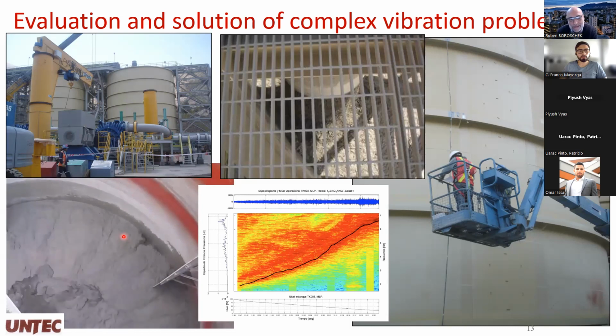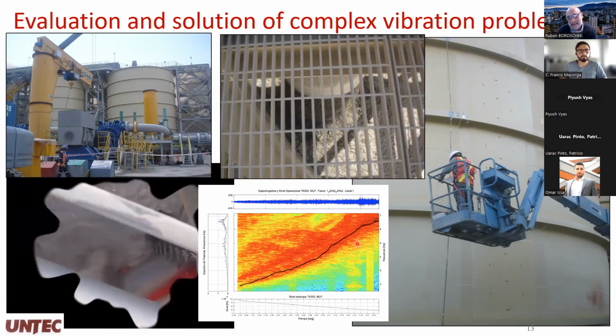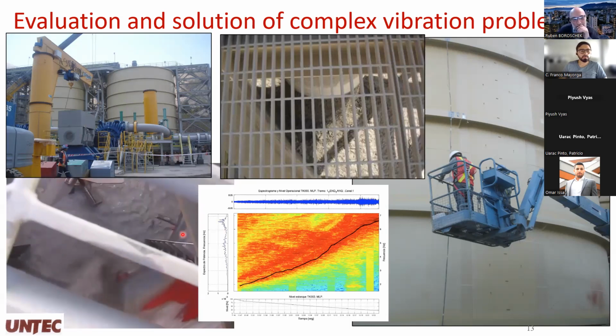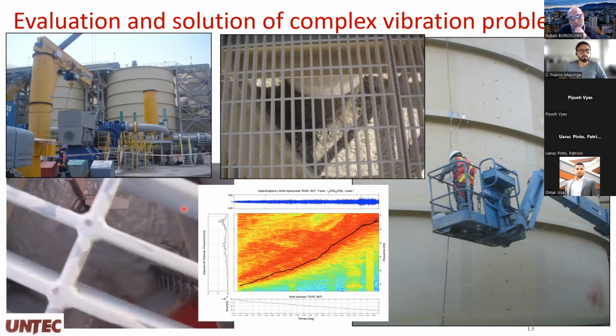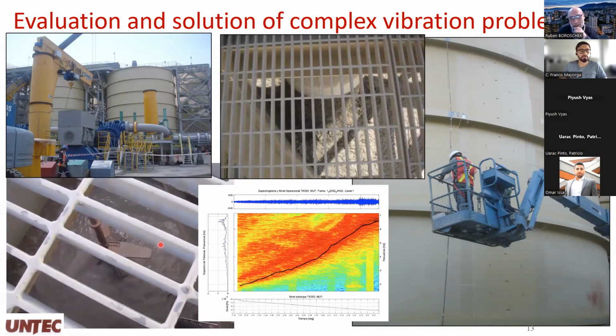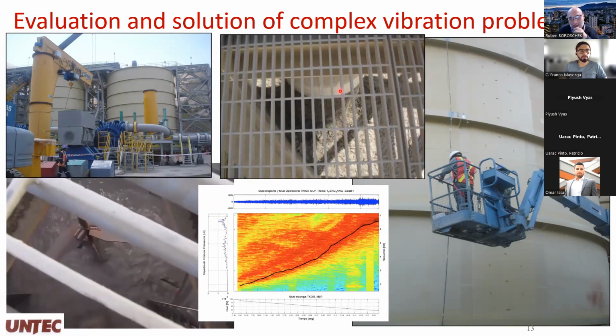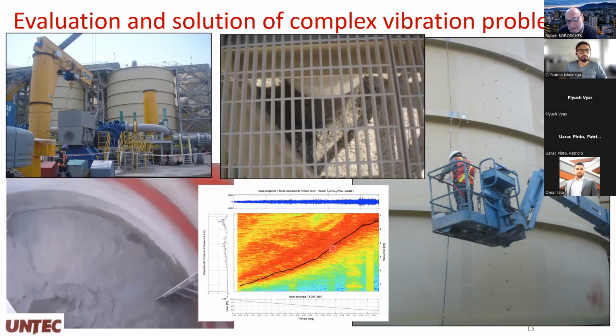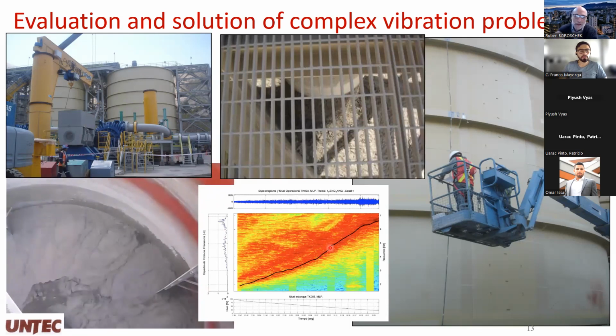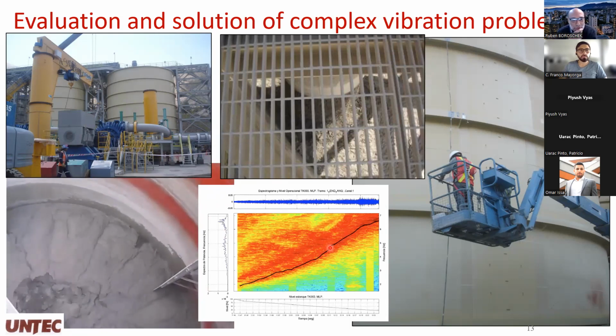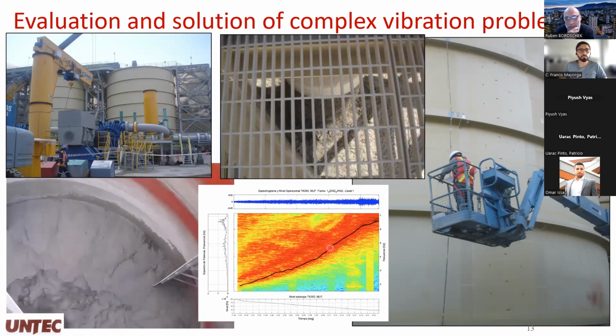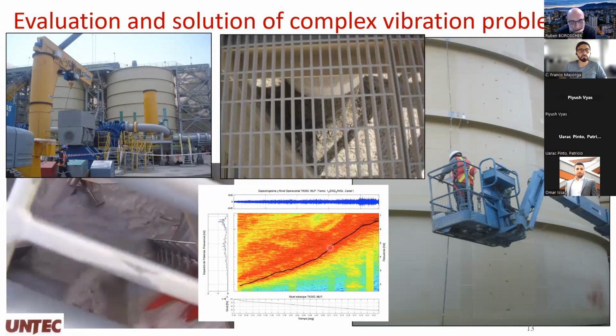So density changes. So we were able to detect exactly in which combination of volume, speed of the motor, and the density of the material the resonance occurs. So we can say, okay, don't stay at that point for too long, so you don't build resonance. And this is how we solve this type of issues.